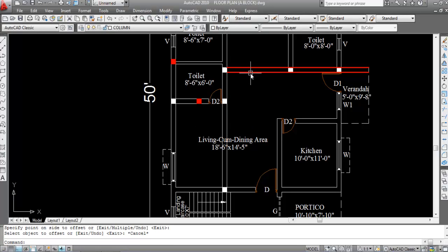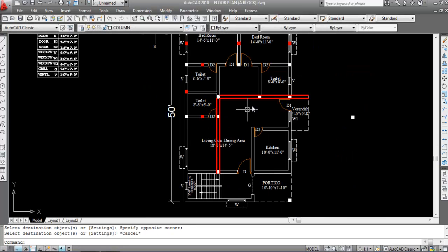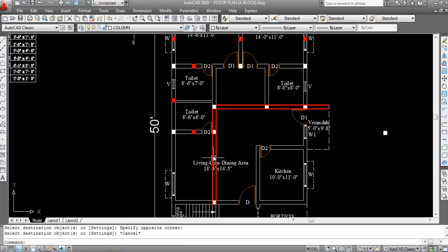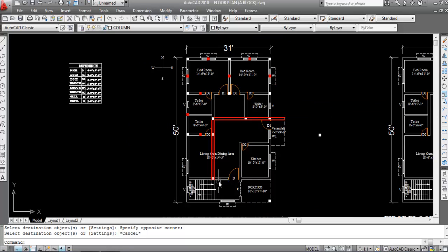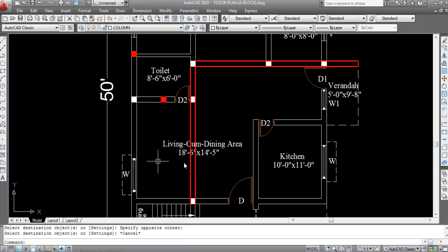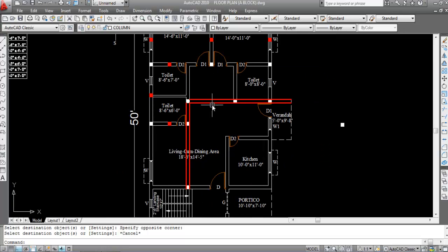Now I'll do mesh properties. Select MA. MA is the shortcut key of mesh properties. Now select this. See, beams will be created like this. Okay. So like this is a cross beam. Okay. So to reduce the effective span, I have created this cross beam by providing a column on the wall. Okay. So this is a column and this is a cross beam. Okay. This is too large. So to reduce the effective span, I have provided a cross beam with connecting columns.